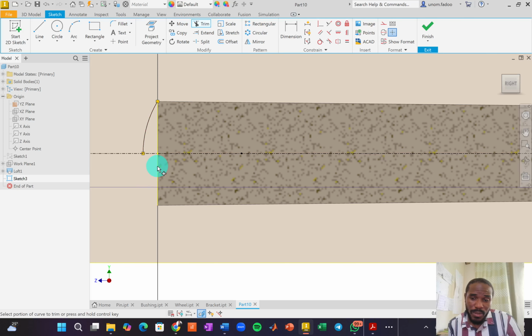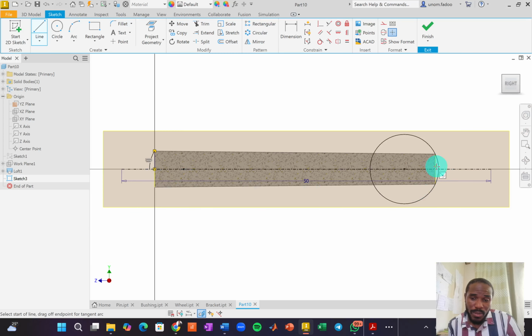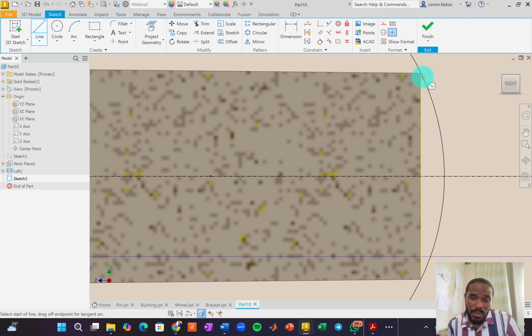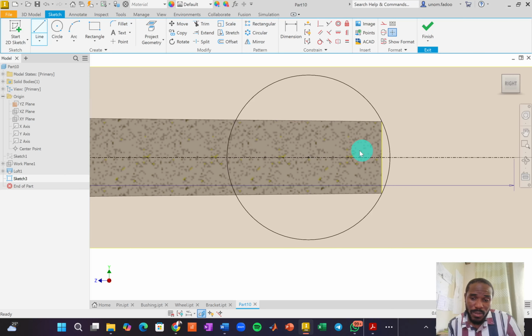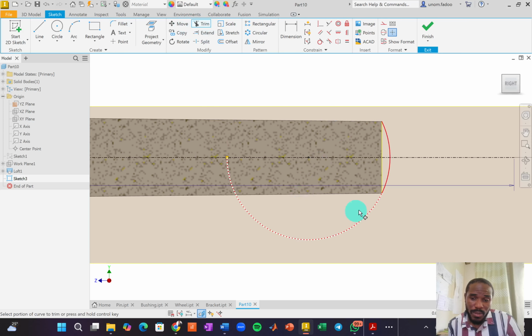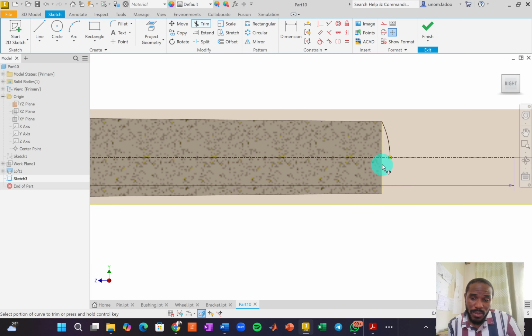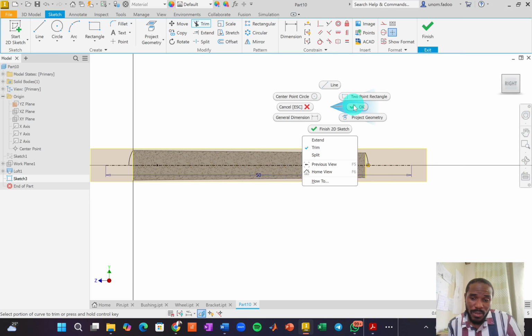All I want is this to go away, this to go away, right? This should also go. Aha, see, I've not drawn the line, so it would not have rotated. I need the line from there to here. Okay, cool. Here also I need a line from there to here. Right click and OK. Okay, where is my trim tool? Pick my trim tool, I trim that off, I trim this off, I trim this off. Okay, great. Right click, OK.